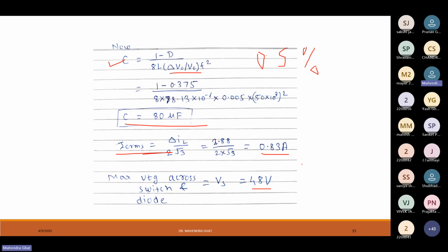The onboard charger has the lower capacity, ranging from 2 kilowatt to 20 kilowatt. In that range, we have onboard chargers for the different manufacturers, and the charger will take single phase AC and charge the battery. So how does it work? Whatever AC is there will first be converted to DC by using controlled rectifiers. Then there will be a DC-DC converter to charge the battery.